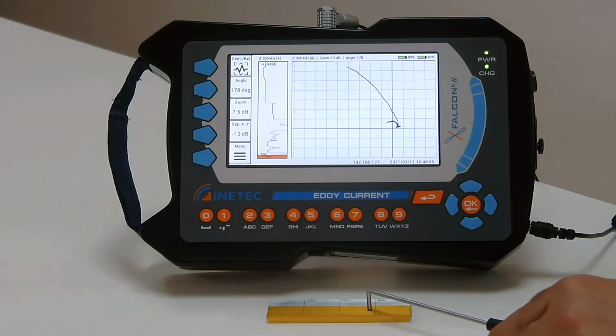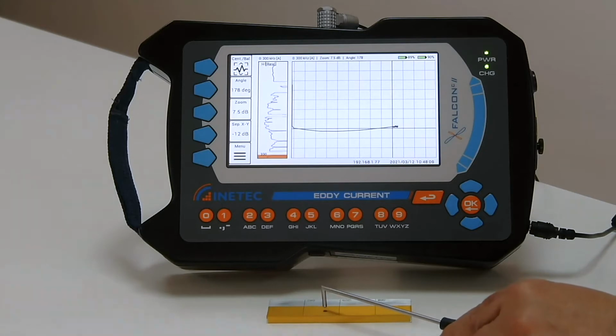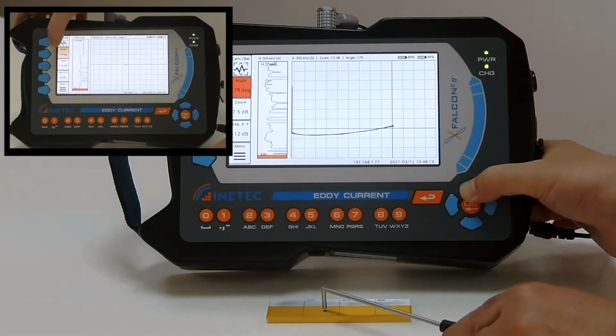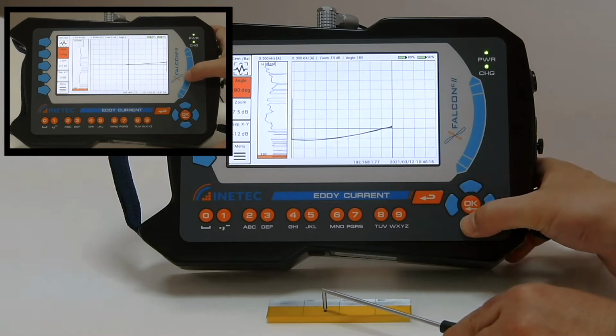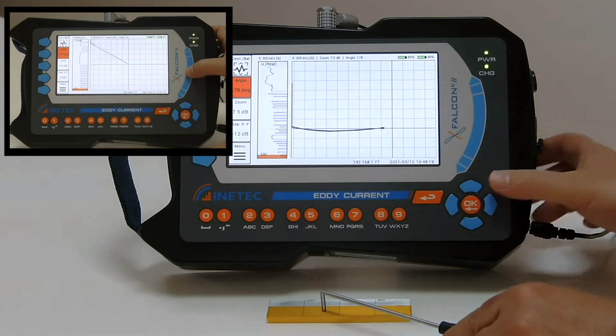Selection is possible in more ways: touchscreen, slider, or keyboard. Proceed to calibration: angle, or rotation of liftoff first, then adjust gain to achieve 100% screen height response.